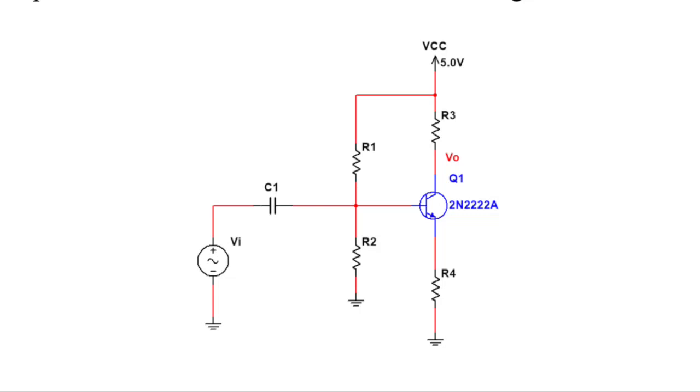For this specific implementation, I have targeted a base voltage of 1/3 of the VCC, so the base voltage is supposed to be 1.6 volts. Considering a voltage drop of about 0.6 to 0.7 volt across the base-emitter junction, the emitter voltage after proper biasing and correct implementation is supposed to be around 1 volt, 0.9 to 1 volt. These are the voltages that I check in conjunction with the collector voltage to justify my biasing condition and operating point of the amplifier.